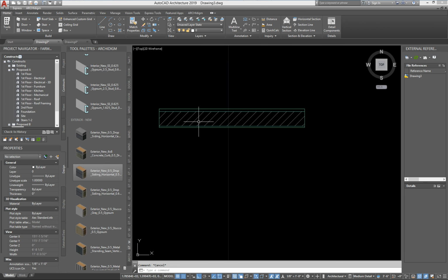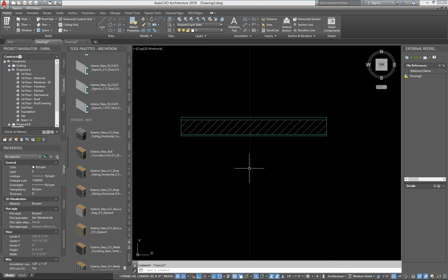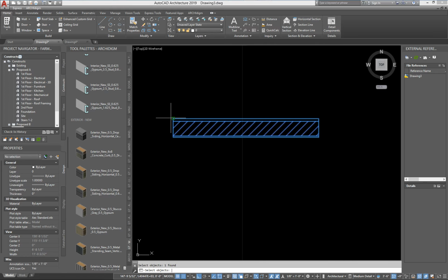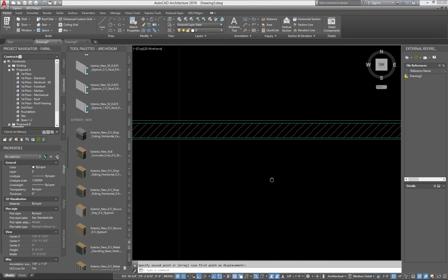Oh, by the way, if you're copying walls from snapping, do the same thing with doors and windows. A safe thing to do is lock your Z. You might notice with doors, if you copy them and you're snapping, they'll jump a certain amount. For me, it's often 18 inches or 14 inches or something. There's something making that hop. And that's just because whatever you're snapping to is at a higher or lower elevation. So locking that Z is a good idea. So now I can copy this wall and not worry that I'm pushing the wall up or down.